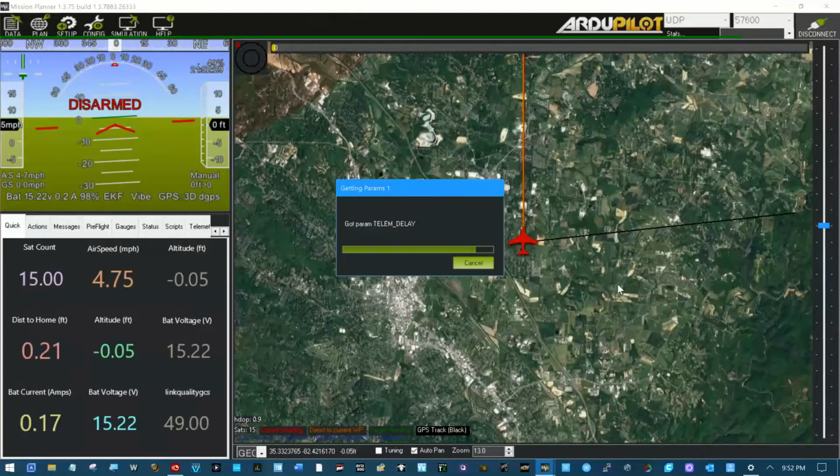Not really, but you can change the distance by using antennas. For every 3 dB that you can increase, you'll double your distance. That's the general rule of thumb for wave propagation. 3 to 6, somewhere in there.